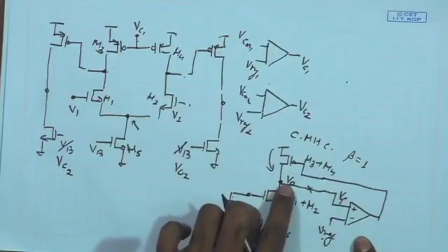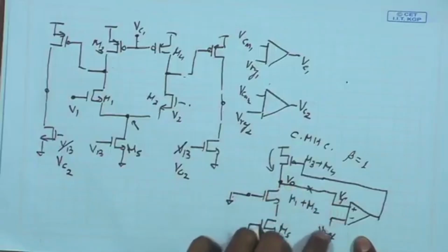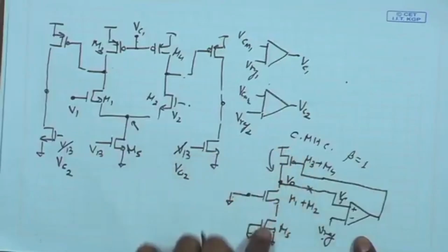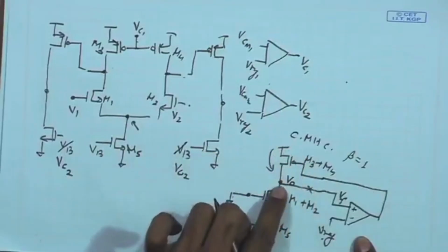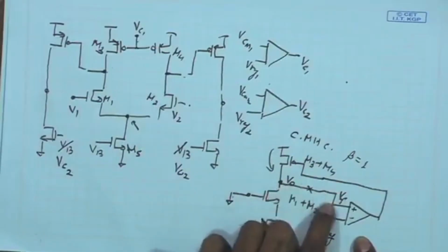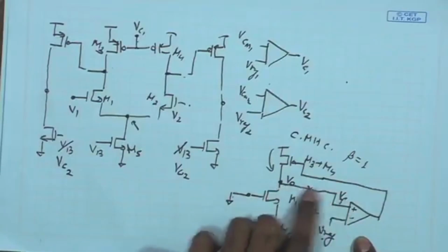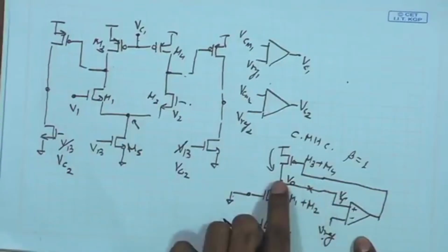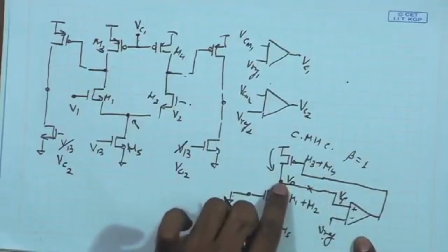So, the output signal after traversing the loop from the differential amplifier going into the fully differential amplifier common mode, the output common mode is applied as it is to the positive terminal. As a result, the beta factor is 1, and we are sensing the output potential of the output stage here. As a result, we are having a shunt connection at the output.